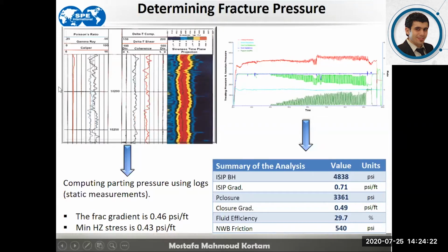One of the crucial elements and factors that would define the performance of the polymer flooding is to understand whether you are injecting above or below the fracture pressure. That requires from you, or from any reservoir engineer dealing with a polymer flooding project, to precisely identify the fracture pressure and to evaluate it in an accurate way. It's better to review several ways and several methods of determining the fracture pressure in order to attain trustable and certain data.